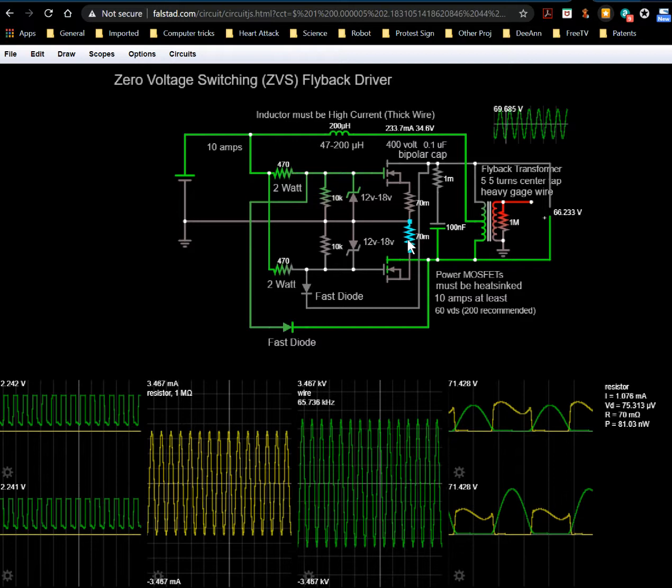You're going to have to come up with a 70 milliohm resistor. That's already built into the, that's the RDS on, okay? So you could actually take this out and have it work as an ideal component, I suspect. I don't think this or these two things are necessary, because this isn't real either. You can just get rid of this, because that's like an ESR, equivalent series resistance, inside of a capacitor. But just ignore this and ignore these two things.